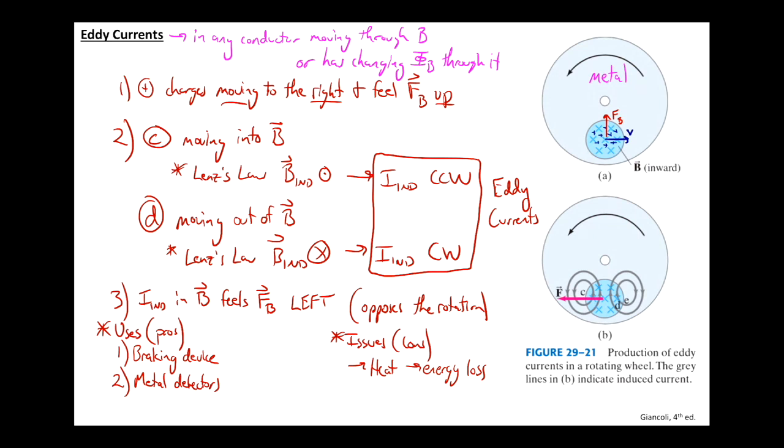One way to do this, depending on how large these eddy current loops are, is that you could create your metal wheel maybe in segments with little bits of insulator in between. And then the currents try to flow, and they're just, well, I can't go any farther. And then the effect sort of dies, okay? So that would be one method, perhaps, to cut down on the eddy current loops and keep energy in the system, all right? Questions about either or any of these three things?